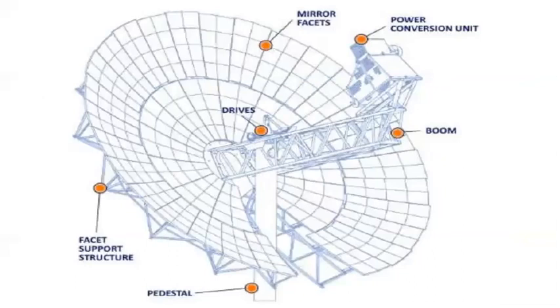A parabolic concave mirror, that is, the dish, concentrates sunlight. The two-axis tracked mirror must follow the sun with a high degree of accuracy in order to achieve high efficiencies. In the focus is a receiver which is heated up to 650 degrees centigrade.